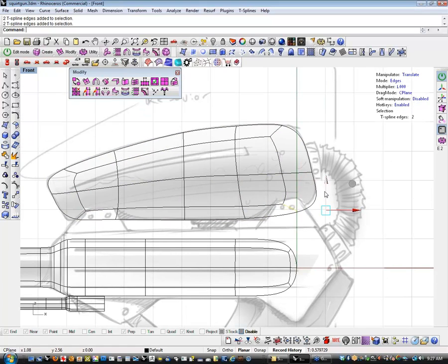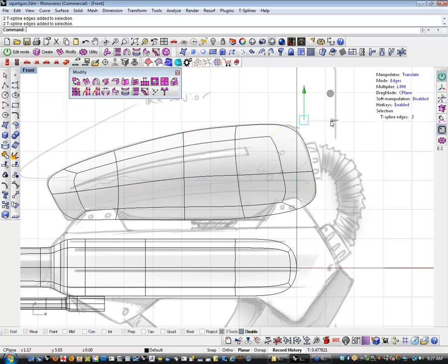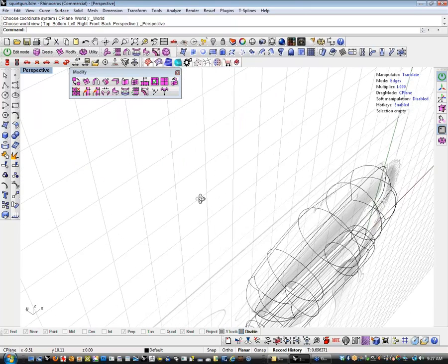On the other hand, it doesn't do fillets very well. So if you want something that has to be a mechanical fillet, then by all means, just intersect the stuff and do it in Rhino. That just infinitely makes more sense than trying to beat your head against trying to figure out how to get the topology to lay down perfectly in T-Splines.